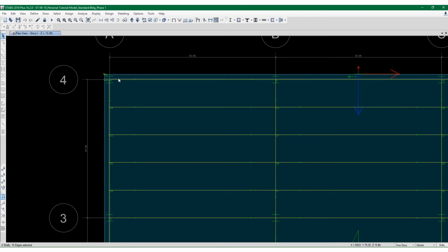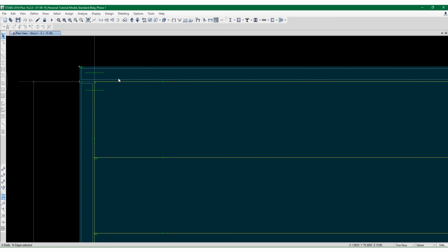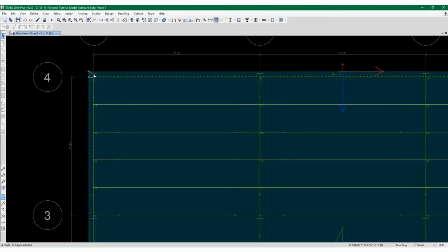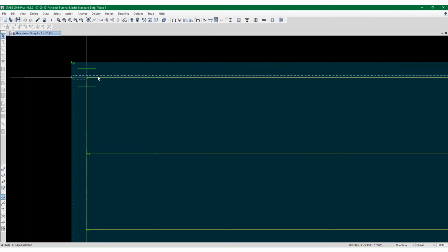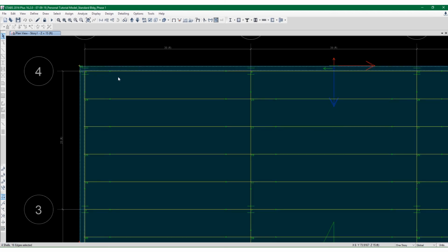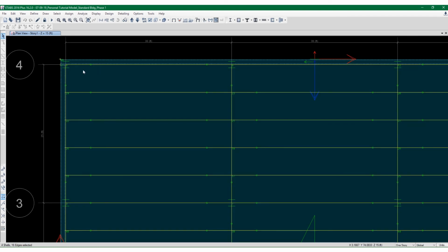So even eliminating this extension right here will not cause a significant error at all, especially when the cantilever is small and the additional weight from self weight is not going to affect you, and any additional weight that occurs from snow or something like that, just rooftop, is a small amount. So you're not going to be affected that much.